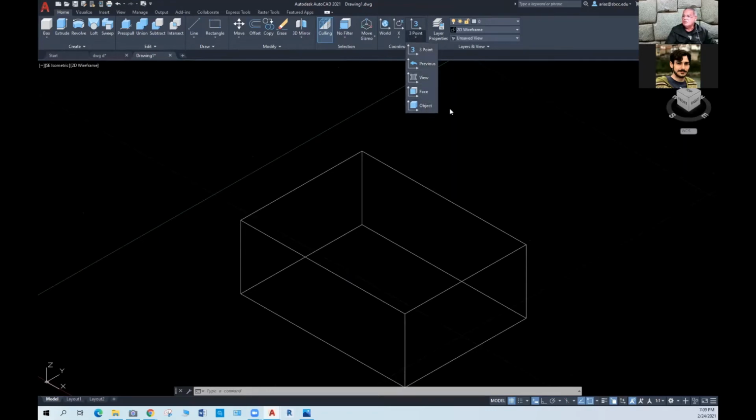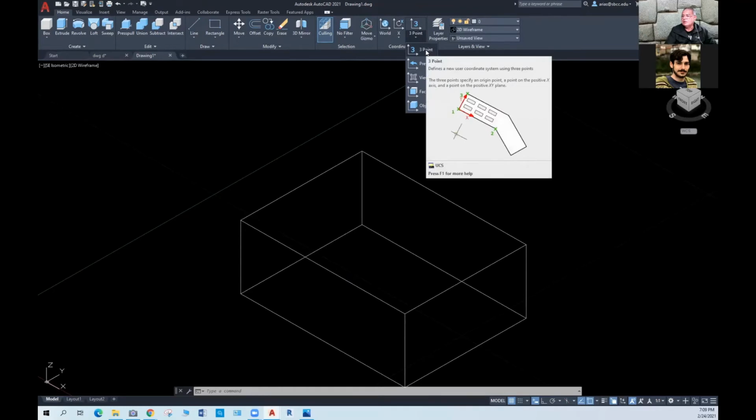And so the one that is more precise and easier to use is this one. This would allow me to relocate the UCS, the user coordinate system, to wherever I want. And in that way, I can always know where the X and Y are located, and then I know where to create the profiles or the 2D content that I need.